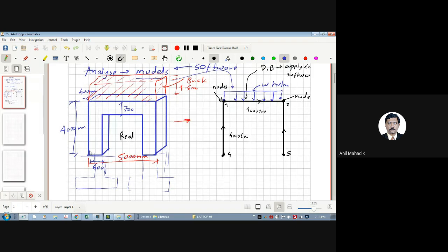these are the footings below the ground, right? Now, at this point, generally we provide plinth beams for tie. So there will be a plinth beam here, right? So we have a choice to model the plinth beams or not. That is our choice. But let's say I want to model only till this point. So generally for frames, you can assume the supports as fixed supports or pinned supports, provided it is a stable structure.